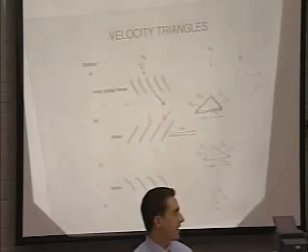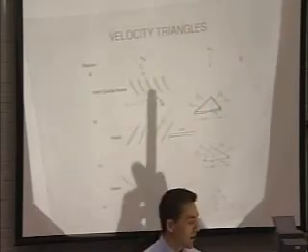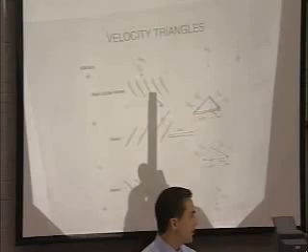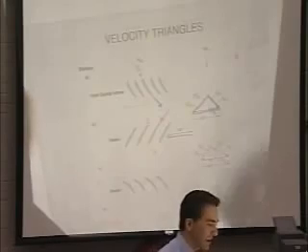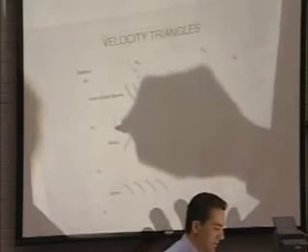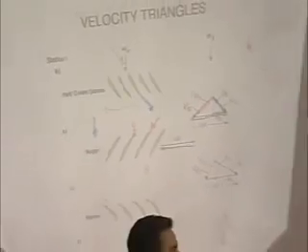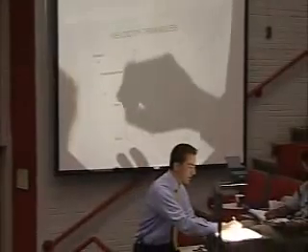No. Think about having the flow coming in straight to these blades into the rotor. So look at the case where the flow comes into them straight, and assume they're not moving. Then you just see the flow coming straight at you. Now assume you start to move in this direction. Which way do you feel the wind blowing on your face? So you start to move in this direction then.